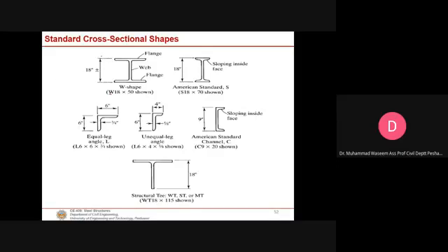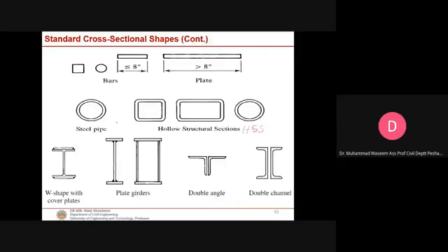For example, you have up to 18 or 20, but the cross section you need is about 40 inches. What do you do? You combine plates and weld them together. This is called a built-up section. Mostly we use these sections for plate girders, the beams on which the demand is very high.